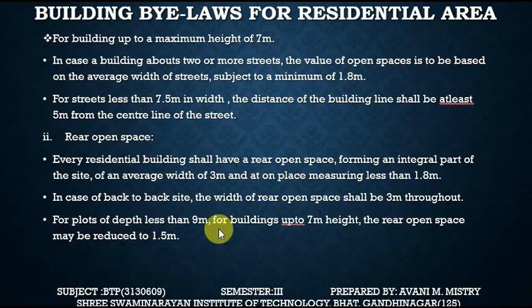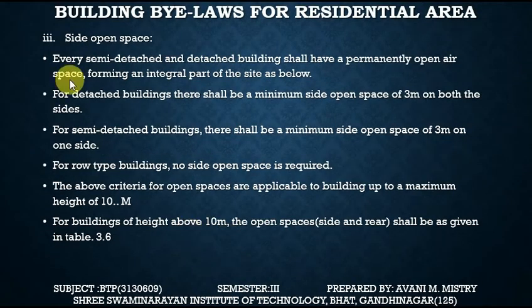Plot of depth less than 9 meter. Okay. For building up to 7 meter height, the rear open space may be reduced to 1.5 meter.